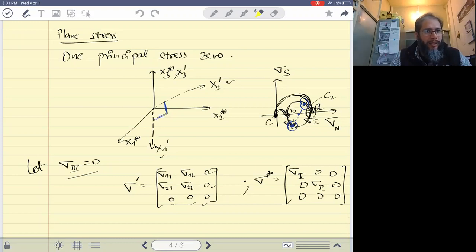It will simply change the direction on the cutting plane. You will stay in the cutting plane, but you will end up pointing in the opposite direction. But sigma n being negative actually means it's pointing inwards. It is changing the volume of the body. It's compressing the body. But sigma s being negative will simply change the shape of the body in the opposite direction. That's the reason we tend to take the modulus of the sigma s max or sigma s value. It's only the amount of sigma s that matters, not the direction. Well, direction matters, but not in terms of it being positive or negative.